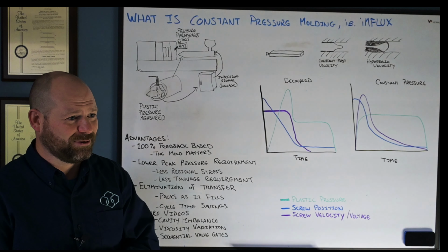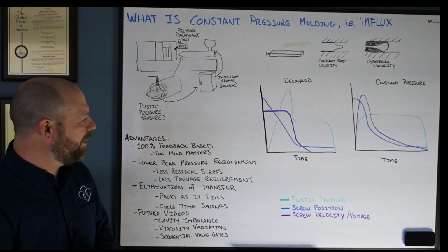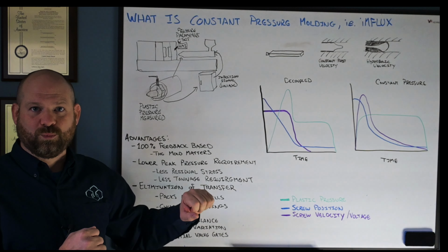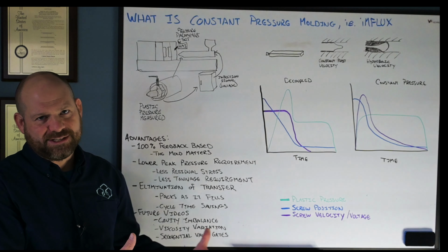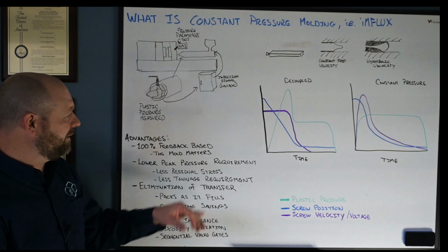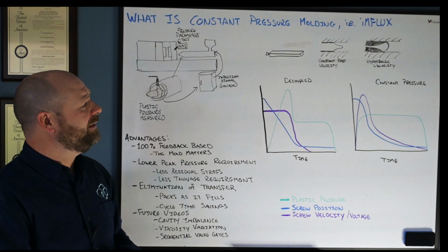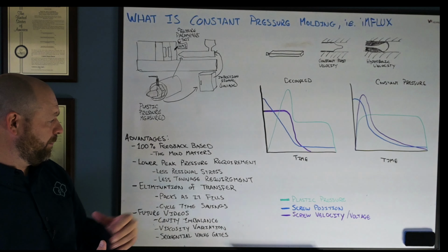One is residual stress. I want to reference a John Bozzelli article in Plastics Technology from a while ago that mentioned he had a break on him in his yard, and it probably had gate seal, right? And what gate seal is doing is trapping a lot of stress around those gate locations in your part. Pressure is not helping that in that instance. You're creating a lot more residual stress around those gate locations in a decoupled process.